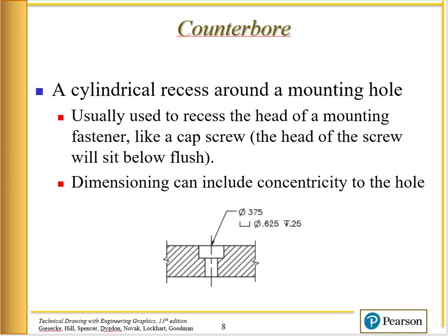There would be other ways to do it. For instance, instead of dimensioning the depth of the counterbore, you could dimension the resulting thickness of this hole here. That's just another way to do it. So that's all for counterbores.